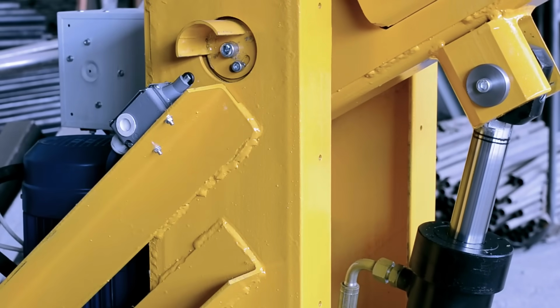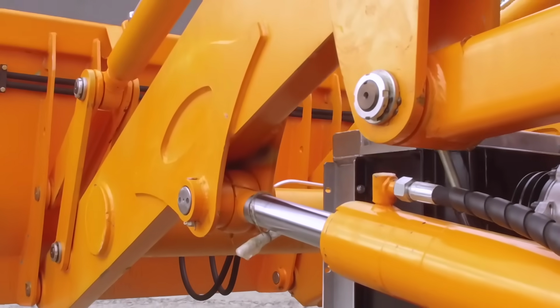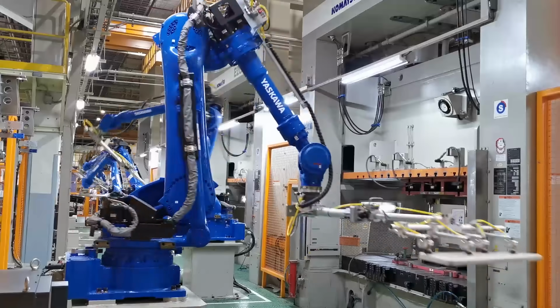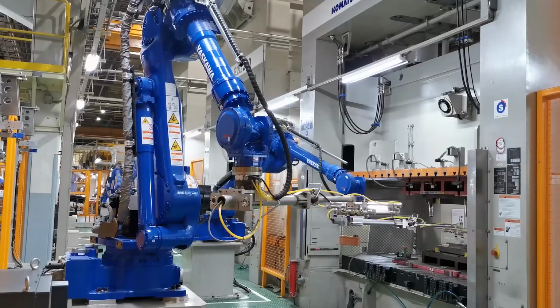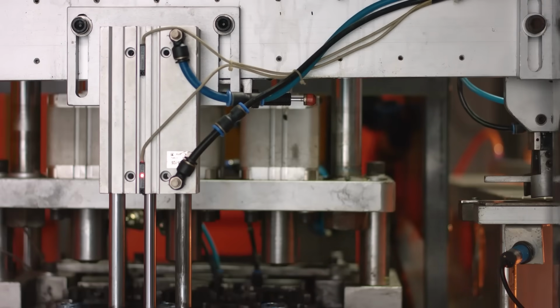Hydraulic actuators are strong and positionable, require non-compressible fluid, and are relatively slow-moving, whereas pneumatic actuators are fast and require fewer components to operate. They are not typically positionable.